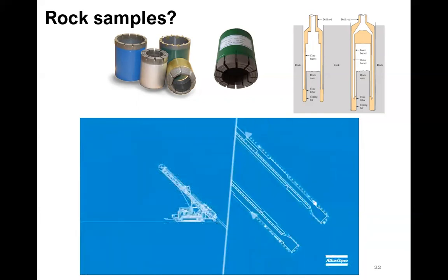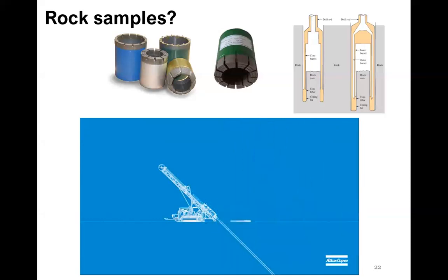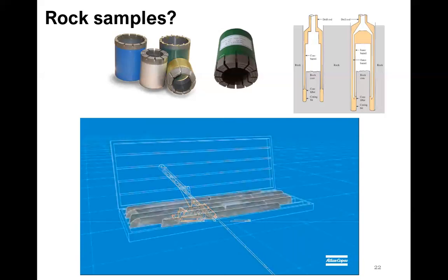During the drilling process, a drilling fluid is flushed down the drill string to cool the drill bit and to transport the cuttings to the surface. When the drill bit is worn out, the whole drill string has to be taken out of the drill hole, regardless of drilling method. Therefore, choosing the right drill bit for the formation is extremely important for high productivity.